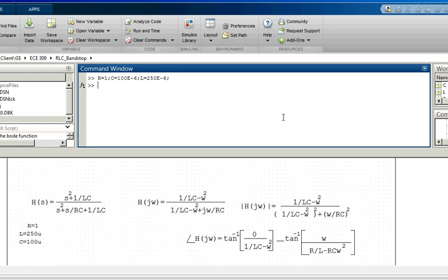Now our transfer function can just be found using TF, short for transfer function, and we're going to define our system as sys1, and that's going to be equal to TF. Now the input arguments of transfer function are really simple. It's just 2 arrays. The first array is going to be the coefficients of the numerator of your transfer function, and the second input argument is going to be the coefficients of the denominator, as you might have guessed. So we're going to write those as follows.